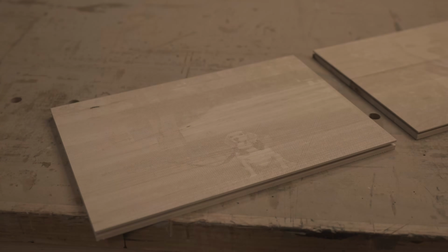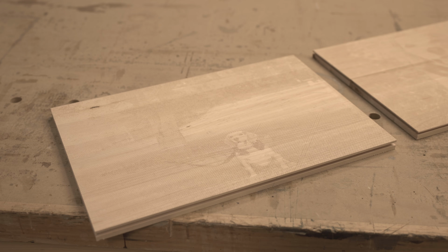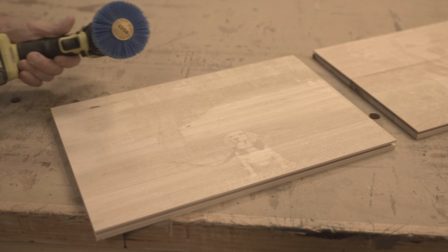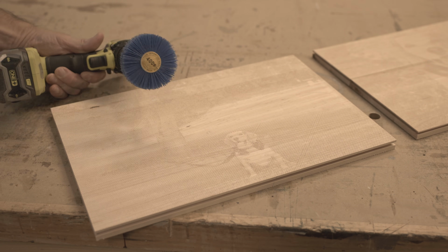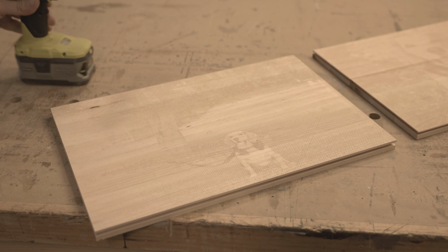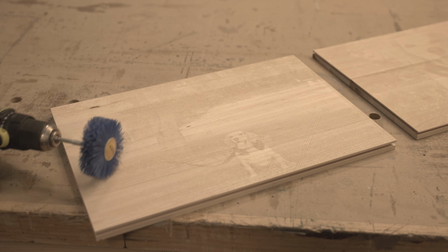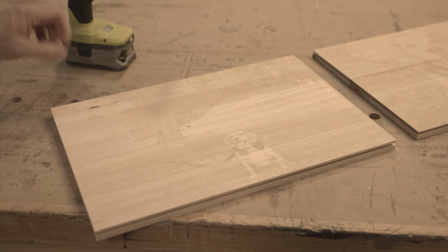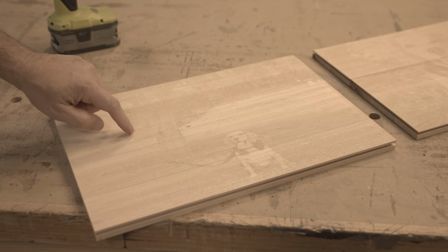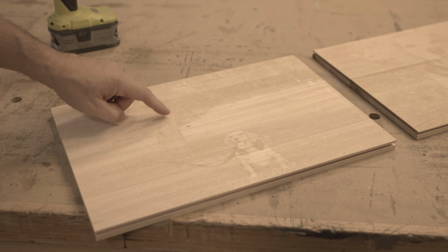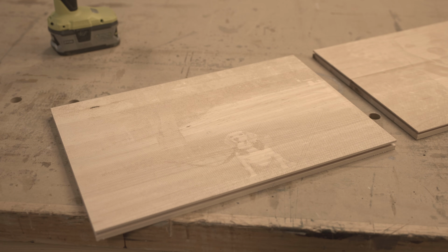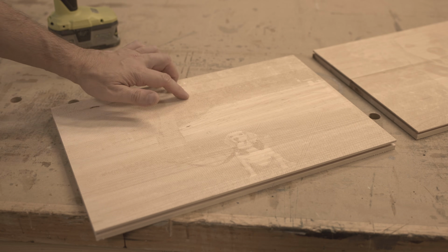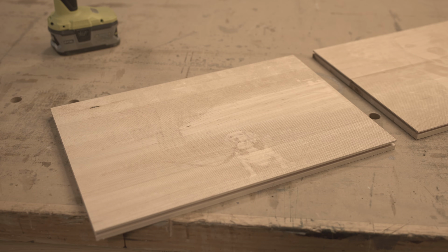Okay, so I've taken the carvings off the machine, and the next step is to use a nylon brush. This is a 400 grit nylon brush, and you go in the same direction as the grooves are cut, like such, to remove all of the fuzzy hairs from the carvings that are still in the grooves. All of that fuzz has to be removed before we seal it. Sealing it will be the next step after this, and you have to remove all of this stuff to be able to seal it.